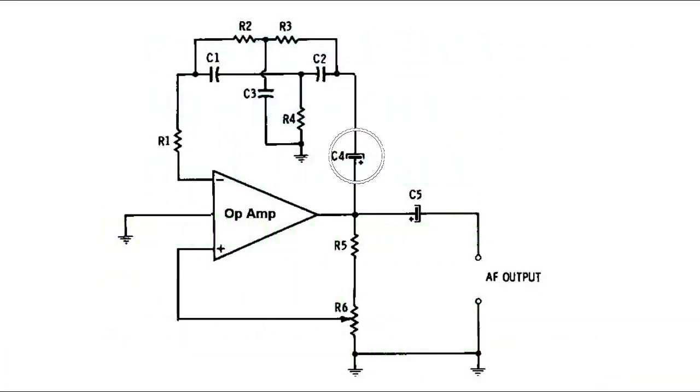Coupling capacitor C4 blocks the DC current and offers a high capacitance with respect to the capacitors C1, C2, and C3. It consequently doesn't have an effect on FR. Resistor R1 offers a high resistance based on the IC's input impedance and helps to decrease loading of the Twin-T network through the IC input circuit.